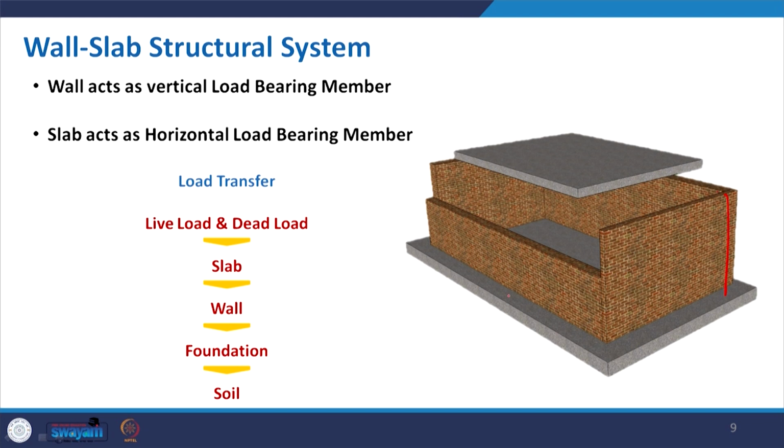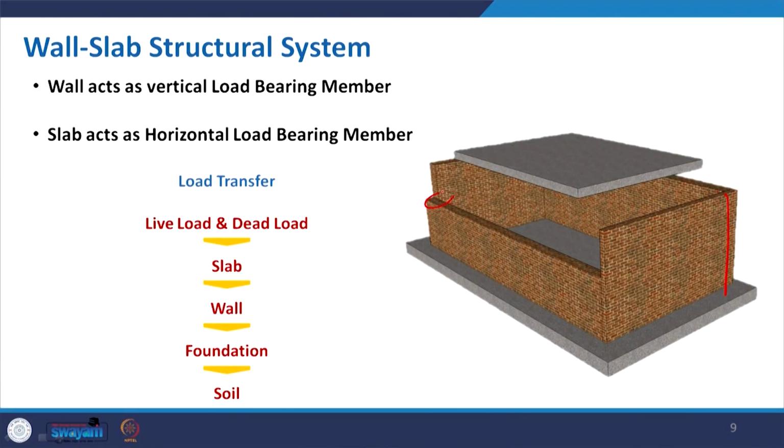It is full wall, and for the load bearing kind of structure, definitely we can change the thickness of the wall at the corner or wherever we go for some kind of connection, accordingly, and on top of it we put the slab. Now, this slab may be of concrete, or in earlier days we used some wooden batten and then sometimes I section, and on top of it we just create the slab.